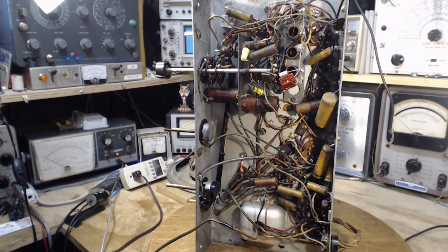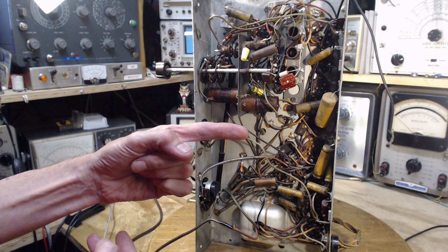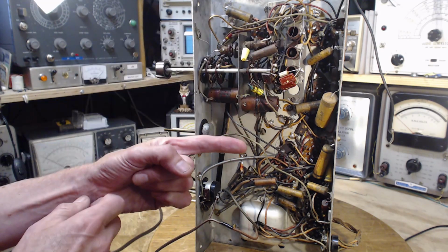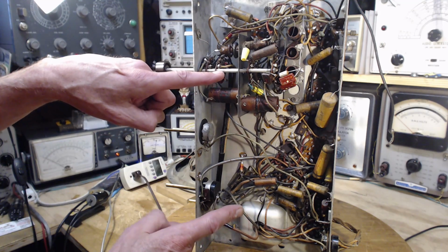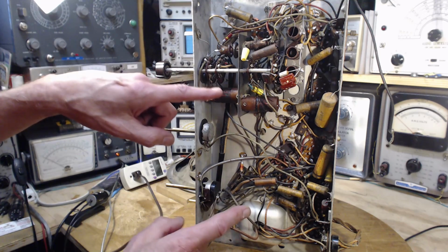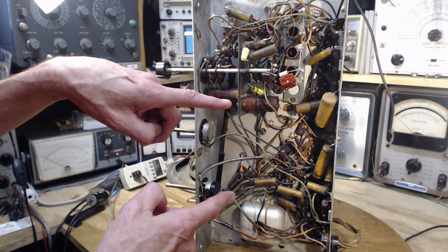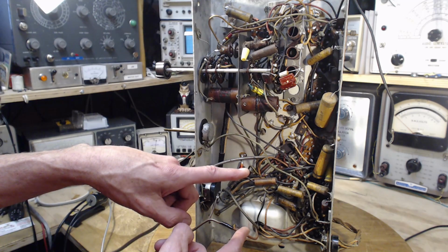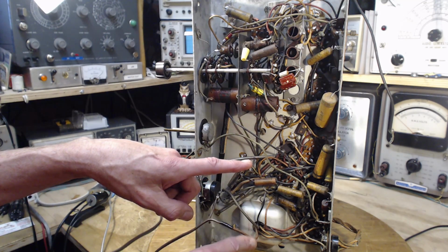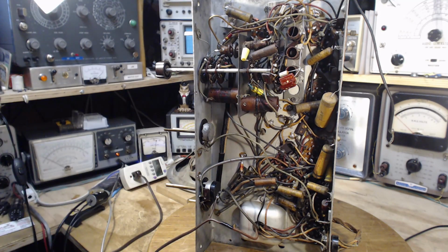There aren't just two frequencies, by the way. The entire antenna signal is being converted to a different frequency. So it's not that you're tuning a particular frequency, like let's say 1010 AM, and then it goes through this tube and gets converted to 455. That's not quite what's going on. What's really going on is that the entire range of frequencies on the antenna, to a fair degree, okay, there is a bit of a response curve involved here, but pretty much the entire antenna signal is getting converted down to around the 455. And so now the whole range of tuning frequencies is down here around 455. One of them may be right on 455, and that's the one that keeps going through the radio. But they're all there. They're all getting converted. Yes, there is some tuning in the front end, but it's not that sharp.